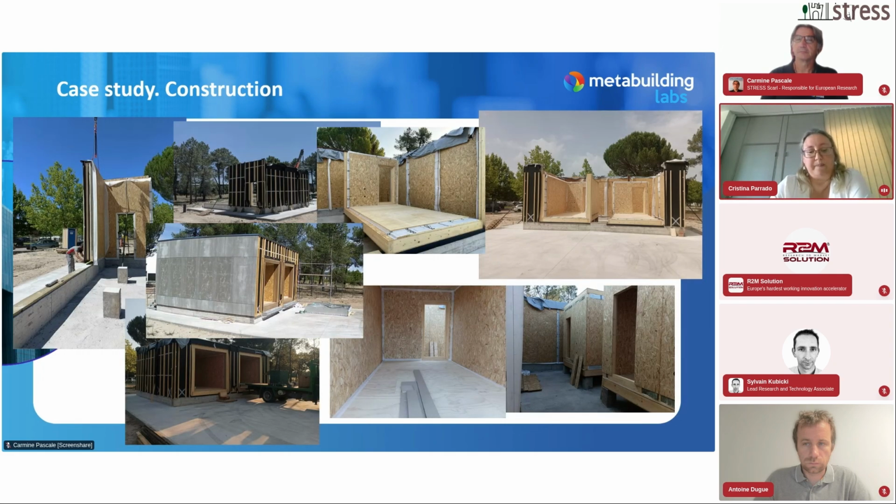You can see more photos of the structure and the rest, with a wooden sleeper around all the perimeter wall. The work began with the assembly of the ward zone, then the cells, and finally the roof. And as you can see in this final one, we had the exterior cladding. The appearance looks like concrete, but it is wood also. The interior of the cells has the minimum size holes required to route the cabling. And we also have a door in the north face that you can see in the picture. That was one of the challenges, because we needed a system with good airtightness, and the U value also had to be similar to that of the wall of the cell. Next one, please.